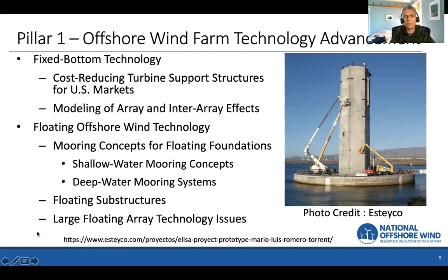For floating offshore wind technology, we've looked at mooring concepts, and also a lot of the consortium's work has focused on shallow and deep water mooring systems. This needs to continue, I think, to some degree, as we realize that the mooring systems that we have right now may not address all of the issues, especially with respect to the size of the footprint in deep water and the possible loading effects in shallow water that would enable us to install floating systems in water depths between 60 and 90 meters.